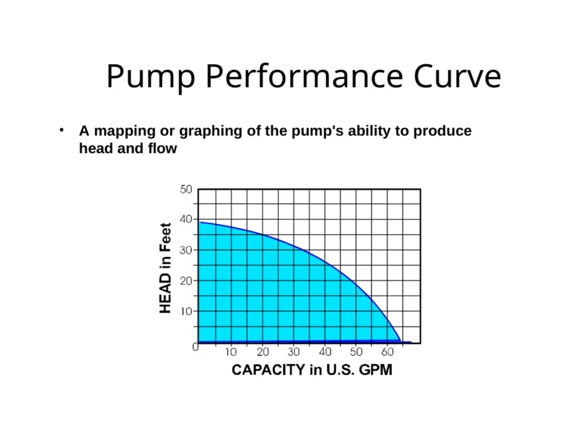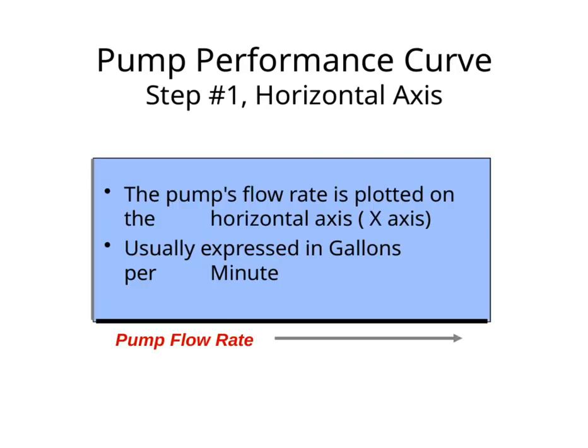Let's talk about the pump performance curve. This graph shows us how a pump behaves, how much head it can generate against the flow it delivers. It's a vital tool for understanding a pump's capabilities, helping us match the right pump to the job. As flow increases, the available head usually drops, and that relationship is what this curve maps out. It's a simple line, but it tells a complex story about efficiency and power.